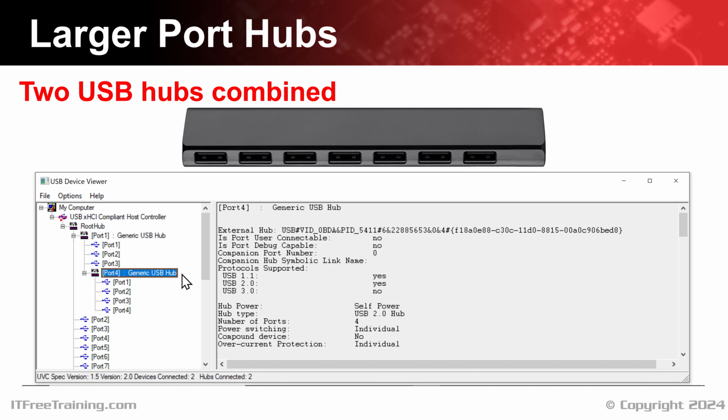You may find that you will have power problems with hubs like this very quickly. This may translate to devices not working or not being detected. You may also find that certain ports will work better than others due to them being connected to the first hub. To get around these problems, I would consider always using an external power supply for USB hubs that have more than 4 ports. Maybe you'll get good results using 7 low-power devices.